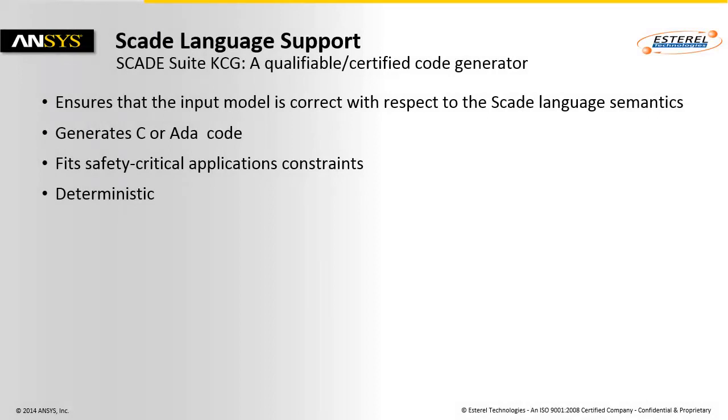The SCADE Suite generator, KCG, ensures that the input model is correct with respect to the SCADE language semantics. It generates C or ADA code that fits safety-critical applications constraints. It is deterministic. An input model always produces the same generated code with the same KCG options.